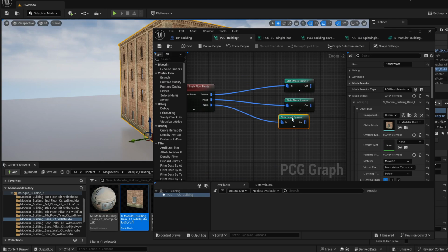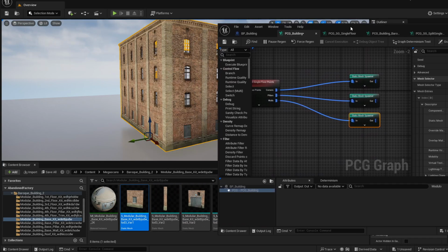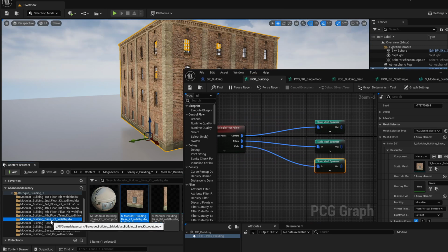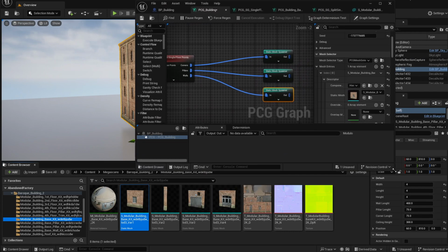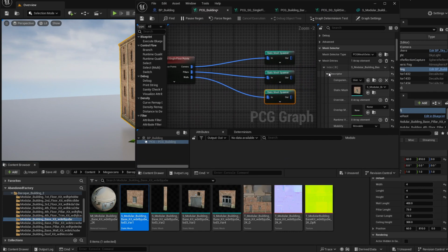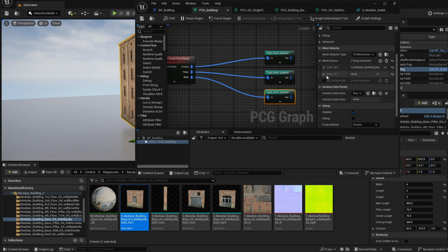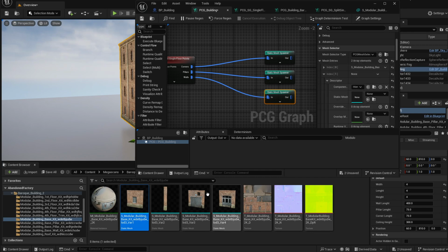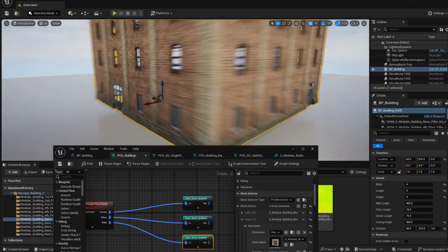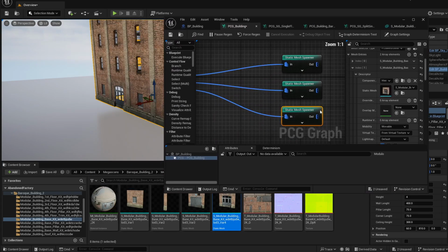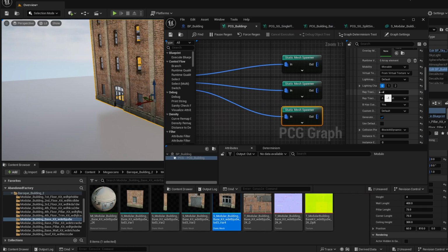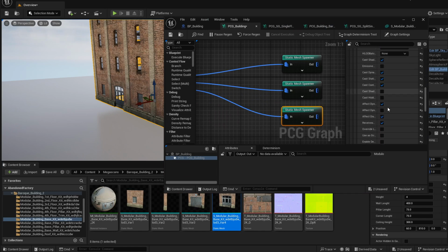So instead of this, what you can do if you want a randomly placed object is go to the folder with the meshes for your building and add a couple of elements. Instead of just having one element here into the mesh entries, you can add multiple entries. For example, I'll add another one, and here into the descriptor I'll connect the door. Now you have a random placement of doors and windows, and you can control the amount for each one with this